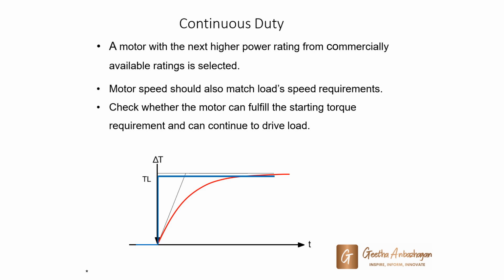For continuous duty at constant or slightly varying load, a motor is selected from a relevant catalog for a capacity corresponding to the power required. Although losses during starting are greater than those under rated load, they may be neglected because starting under continuous duty is very infrequent and has practically no influence on motor heating.